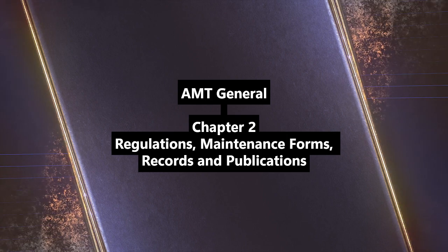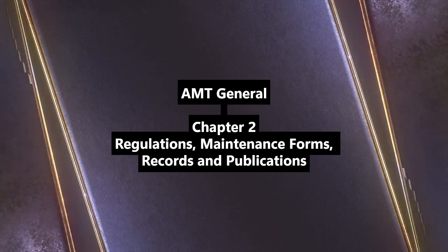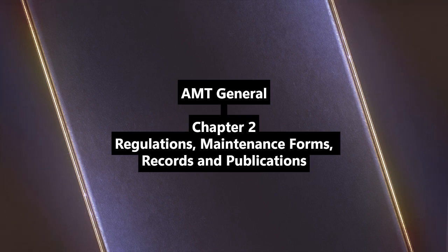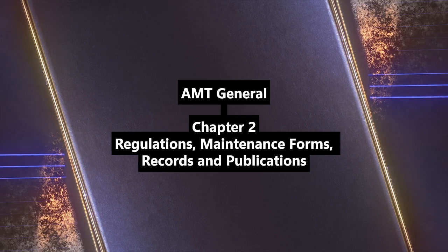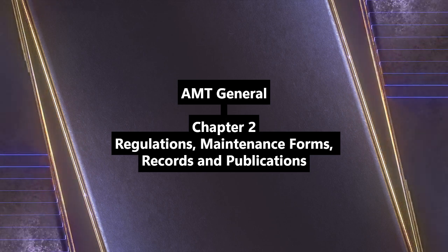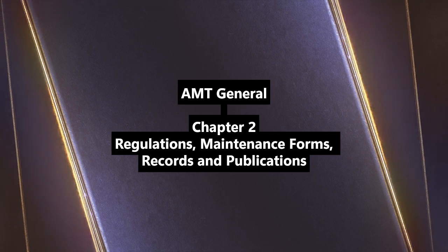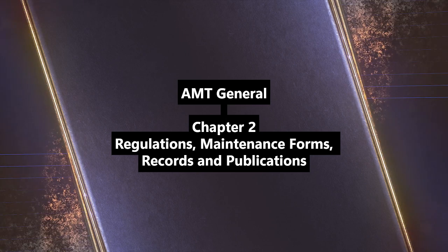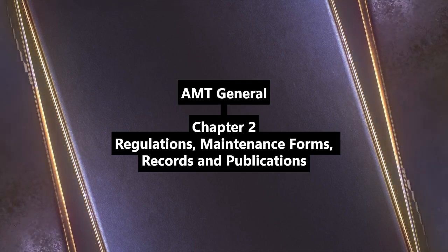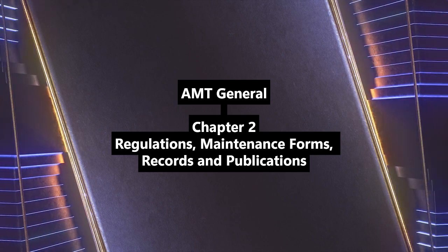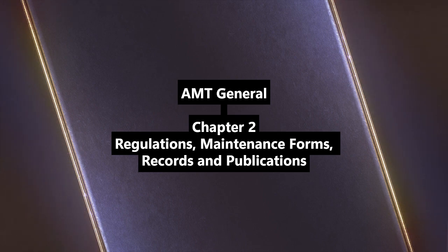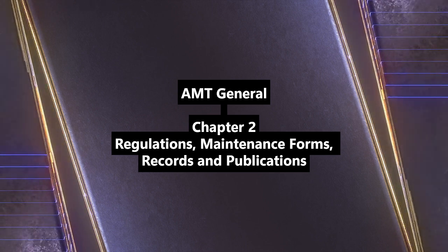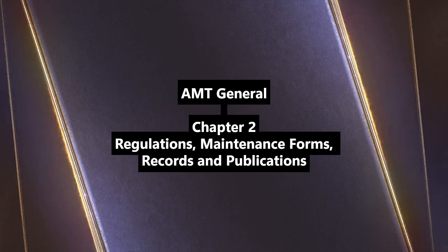Got it. And finally, how does the FAA manage all this oversight with limited resources? Through 14 CFR Part 183 representatives of the administrator. This covers the FAA's designee program, started way back in '62. Using private sector experts. Exactly. People authorized to act on the FAA's behalf due to budget and personnel limits. Think medical examiners, pilot examiners, DPEs, mechanic examiners, DMEs, engineering reps, DERs, manufacturing inspection reps, DMIRs, airworthiness reps, DARs. So extending the FAA's reach through qualified individuals in the industry. Precisely. Each has specific roles in certification and oversight.